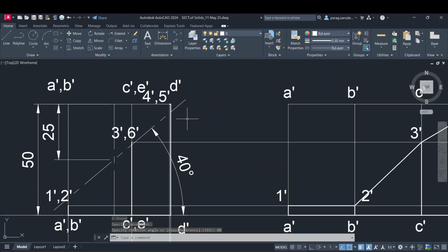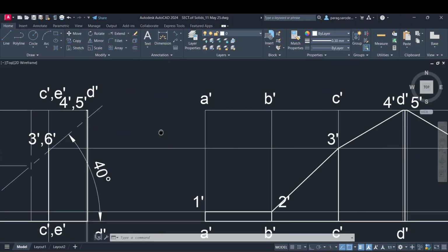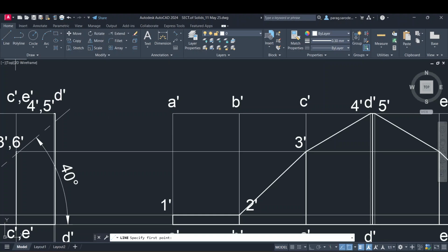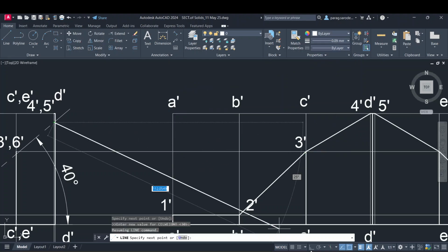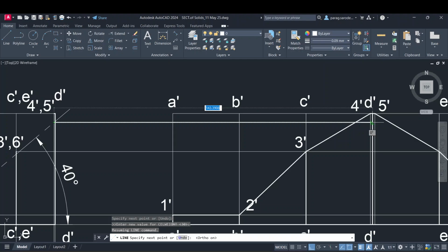If the angle is 40 degrees, you can see all the vertical faces of the prism getting cut. So in this case, whenever we draw a development, it will be only like this. A line will pass through this. So here we will get the cut, and this development, instead of the 4, will be directly connected to this particular point.